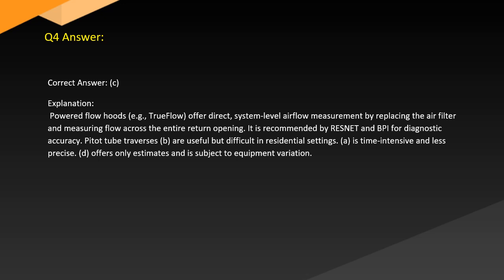Answer. Correct answer: C. Explanation. Powered flow hoods, e.g., TrueFlow, offer direct system-level airflow measurement by replacing the air filter and measuring flow across the entire return opening. It is recommended by RESNET and BPA for diagnostic accuracy.